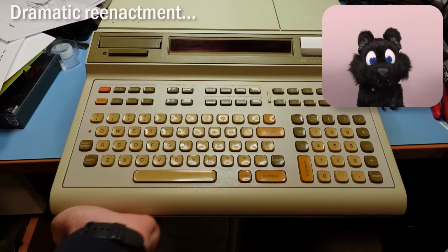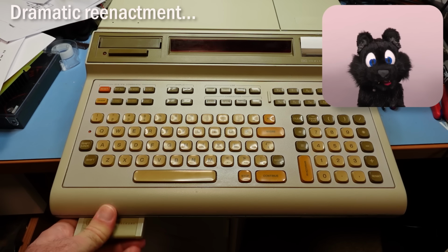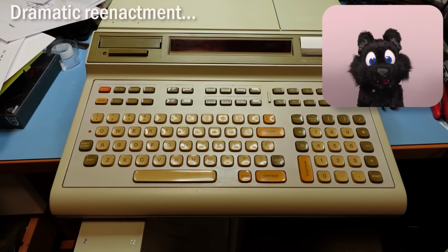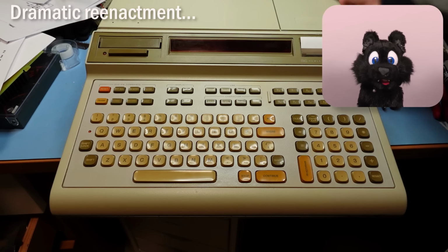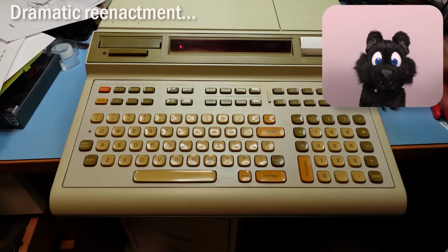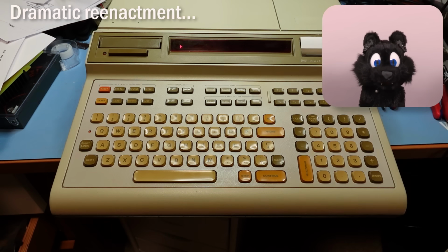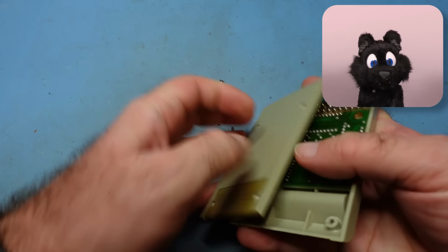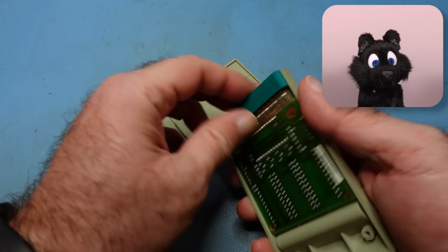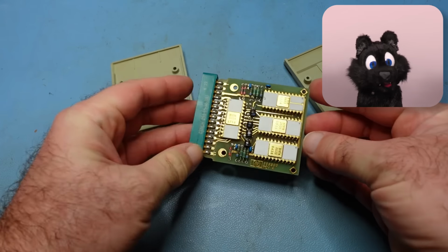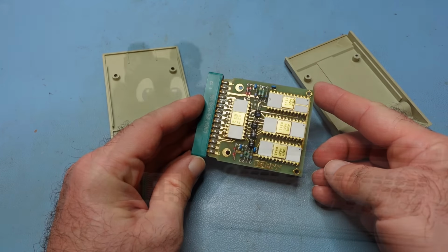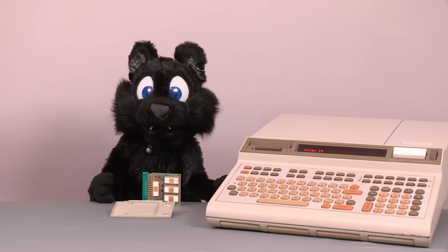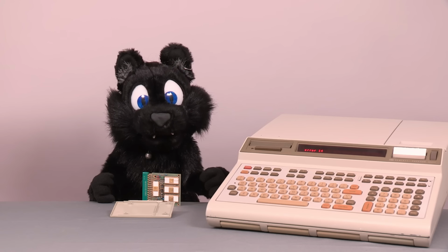There is a slim chance that something is wrong that only gets triggered when the I/O ROM is active, but since the I/O bus is working fine even with the error 14, keyboard, tape and printer work flawlessly, I think the ROM is the reasonable assumption. And that brings me to the next sub-project, a generic ROM replacement card.